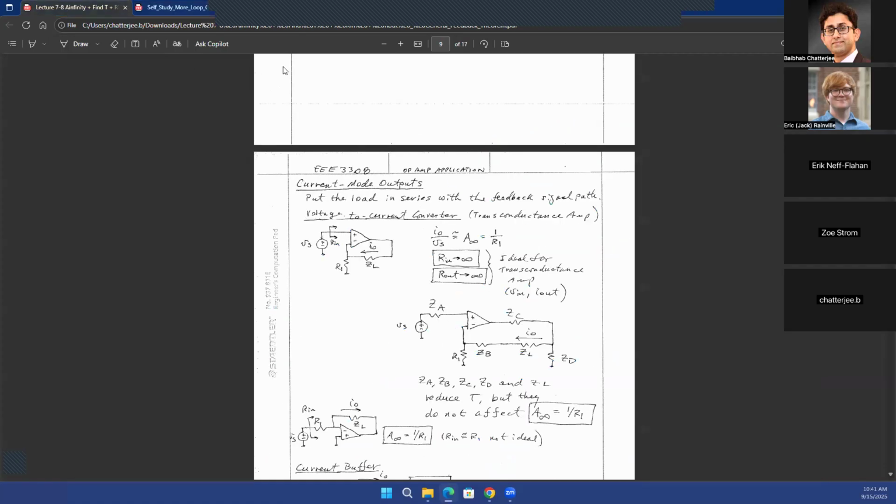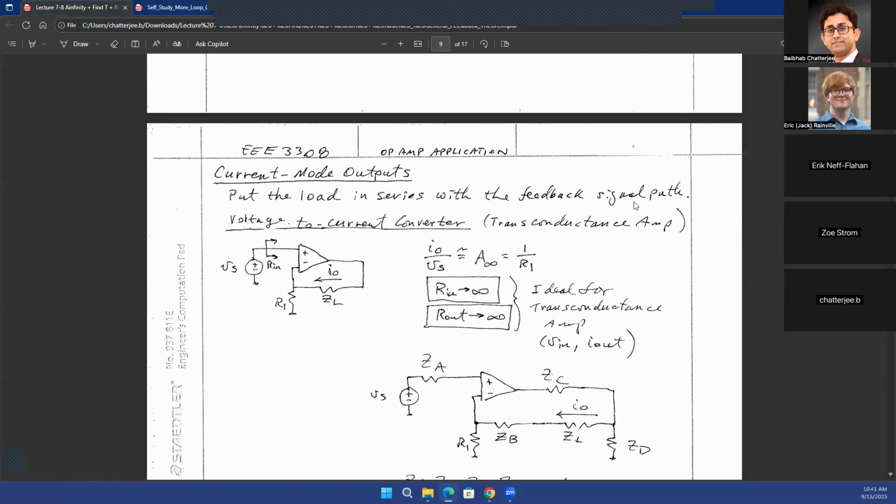All right. So in the last lecture, you looked at how to find out the loop gain, the total loop gain, which is A times beta in any non-ideal op-amp configuration. Non-ideality can mean that you have a finite input impedance, a non-zero output impedance, and a finite gain. We looked at methods to take care of all of those, how to find the loop gain, and depending on the loop gain, what the closed loop overall transfer function of the system would be.